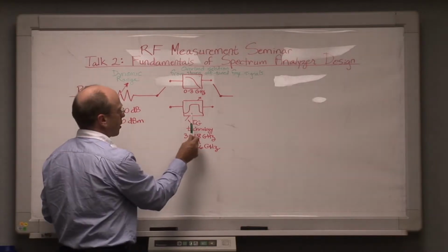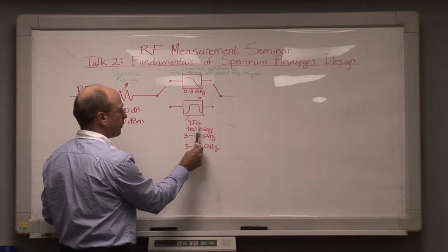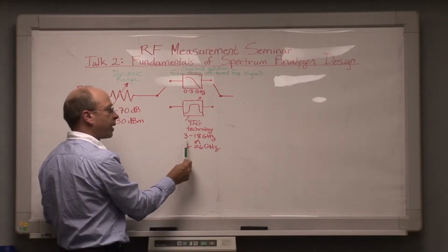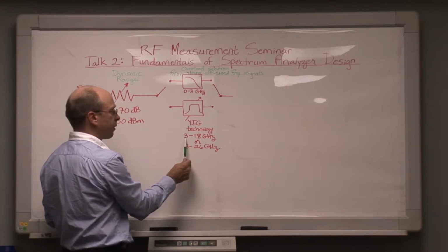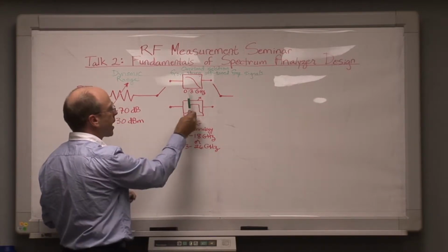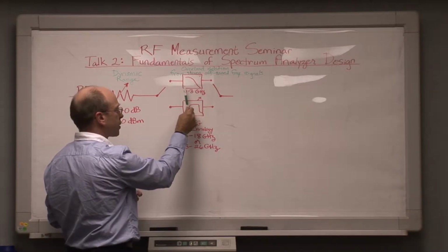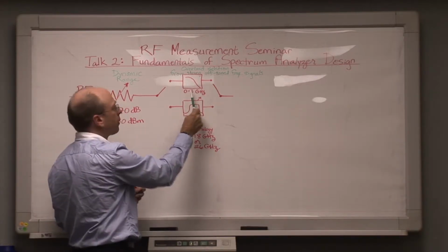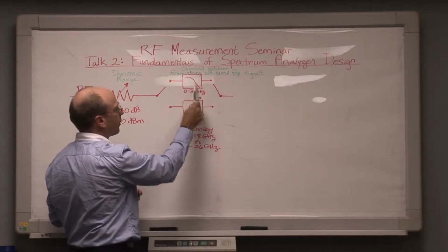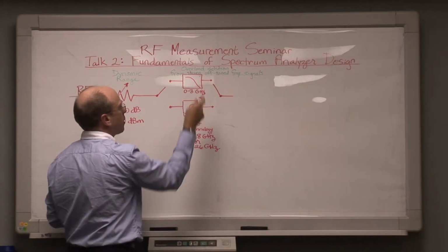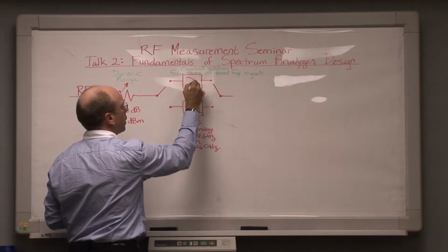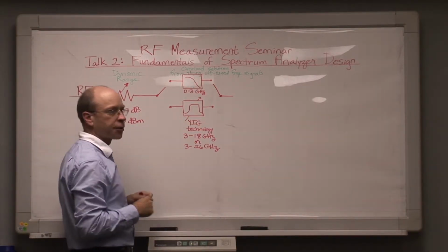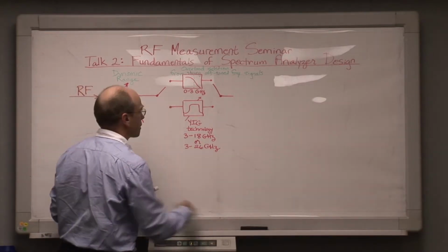Many spectrum analyzers are specified as having YIG tunable filters at the front end, but what they often don't tell you in the sales literature is that that filter only works if you're tuned to frequencies above 3 gigahertz. So be aware that you can overload the spectrum analyzer with strong signals below 3 gigahertz while you're measuring other signals on different frequencies below 3 gigahertz, and that this front end filter, which is a low pass filter that cuts off at basically 3 gigahertz, will not prevent that problem if both the signal you're measuring and the strong overload signal fall below 3 gigahertz.